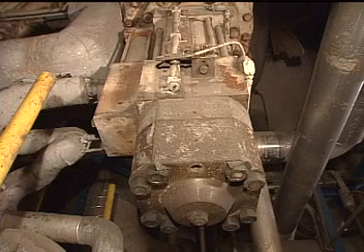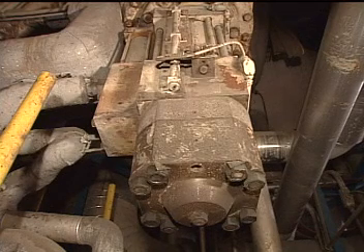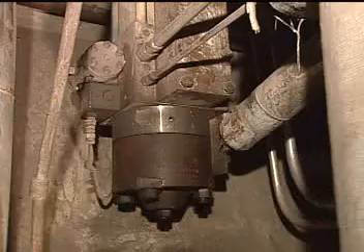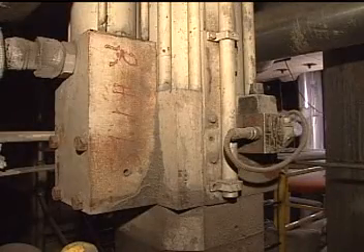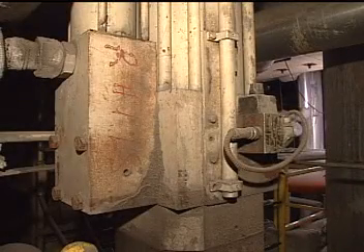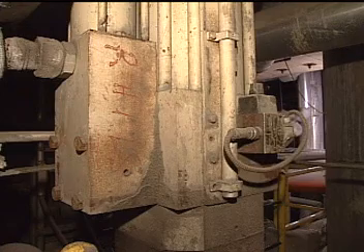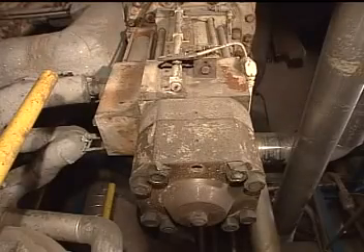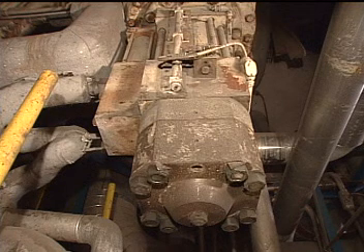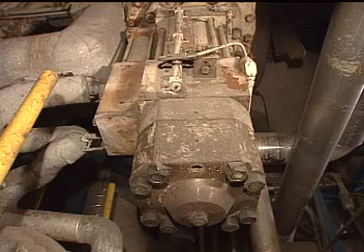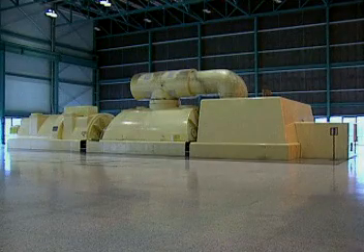As we've said, reheat steam systems also include reheat stop valves and intercept valves. These are specially designed valves that are operated by hydraulic cylinder actuators that are controlled by the turbine control system. The functions of reheat stop valves and intercept valves are similar to those of the main steam stop valve and the control valve found in a main steam system. One of their chief functions is protecting the turbine from overspeed.